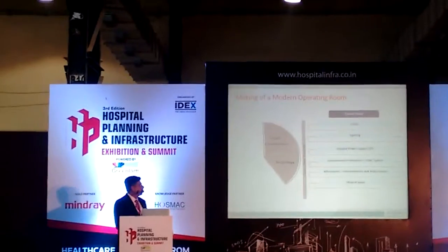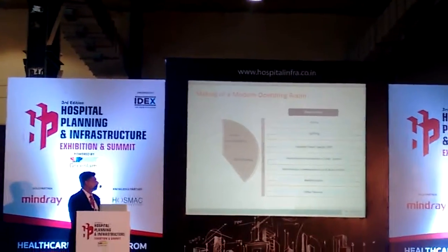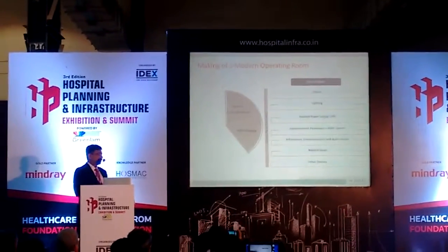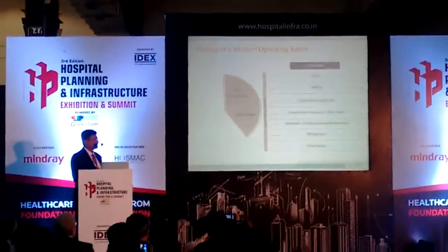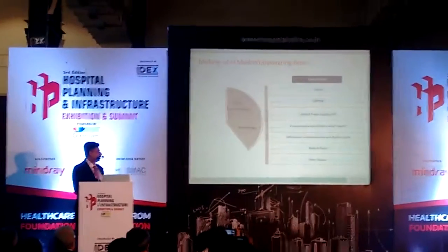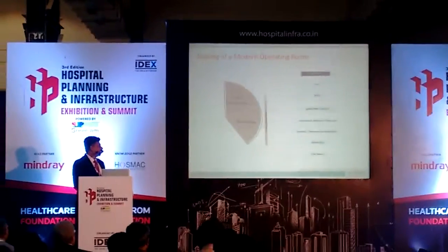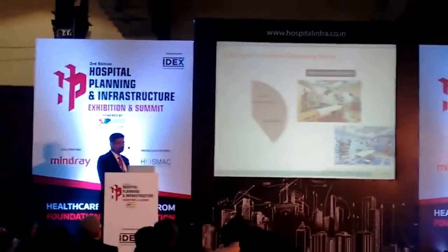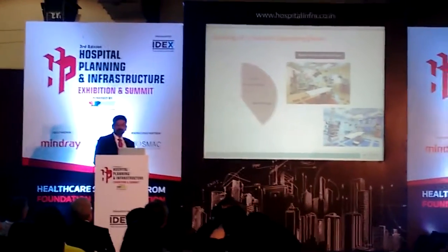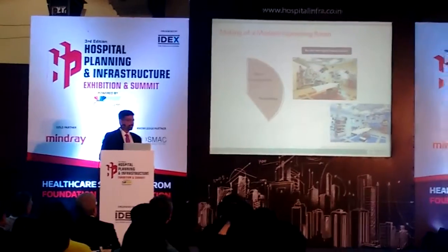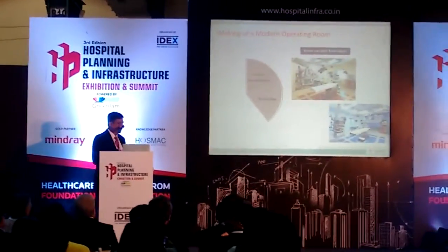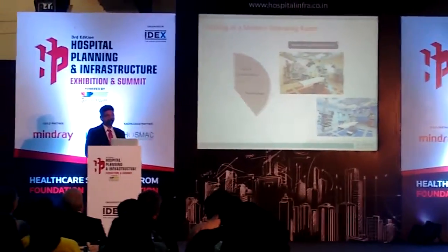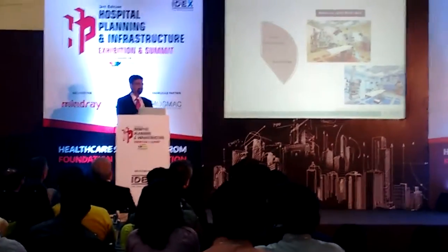The surgical control panel will have a clock, which is a general standard practice, lighting, and isolated power supply. I hope everybody is aware that no more grounded power supply is being used. Environmental parameters of air conditioning will be taken care of, along with information and medical gas systems. Boom, some lighting controls. Lights have gone for a tremendous change. Again, LED lights have come in, with the lux levels and the kind of efficiency, and also in terms of air conditioning, it has been a great advantage using LED lights as against the earlier ones.